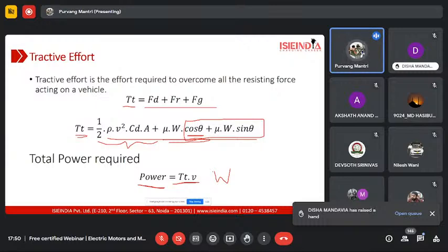But it was recommended to not use the first gear, because the motor initially has high torque, and the main requirement of first gear in an ICEV is that it provides high torque, because the torque curve of any ICEV is not flat.